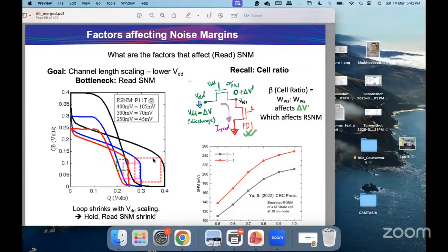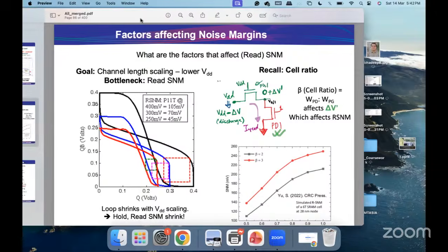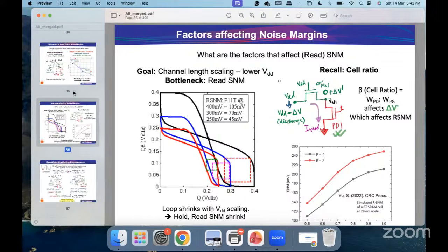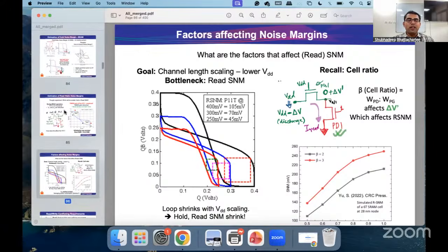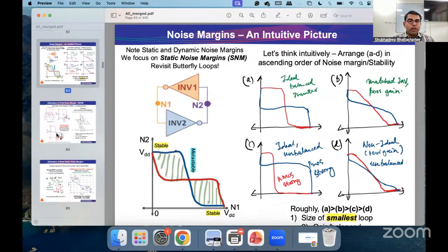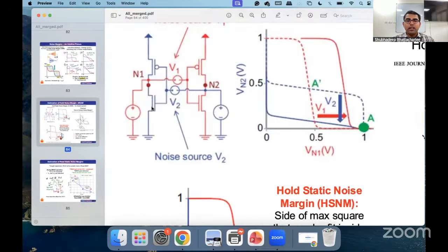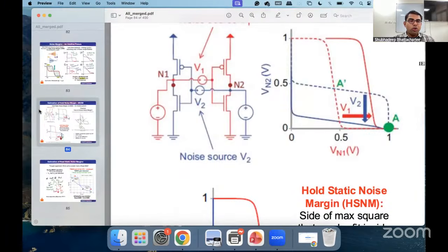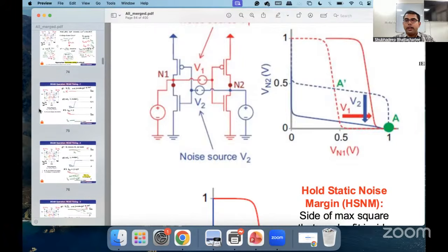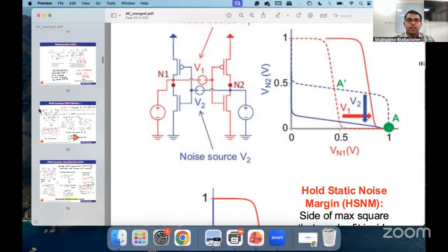Yeah, somewhat. But just one more counter question. If in a cell we are making the NMOS stronger, that means we are making our access transistor also stronger. So there will be a trade-off between that. I think we should stop here. There are different things. You're talking about process variations, so we will not confuse two things: one is process variations and the other is intentional sizing.